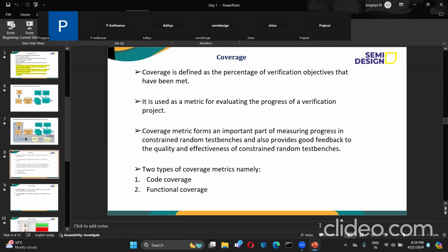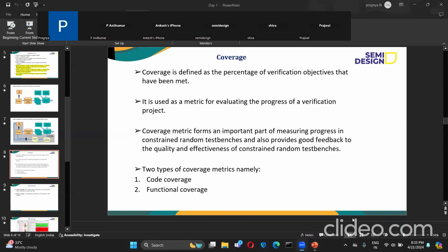So even though test cases are passing from all the suites and all the blocks, coverage is not hitting. What can we do at that time? I think the 40% coverage, or whatever percentage we are getting, might be for the functionality that we have written. Once we get the VDB file, we need to check whether a bit is toggling, whether the corresponding branch is covered, or the FSM is covered. Basically, we need to see where we are actually missing.